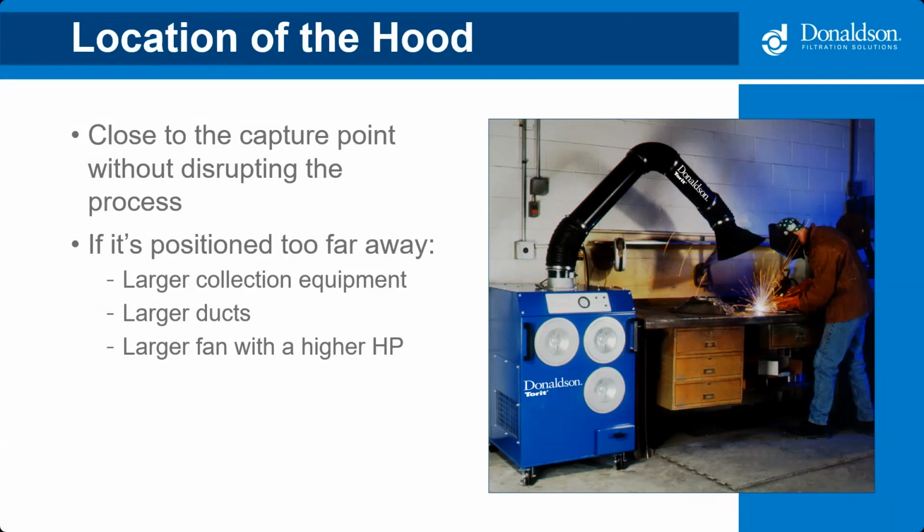Consider a vacuum like in your house. To pick up the debris from the surface, the vacuum head must be close to the contaminant or it has no effect. Same thing with a bell mouth hood. A hood positioned twice the distance from the generation point rather than the capture point will need to draw approximately 4 times the amount of air to produce the same capture efficiency.